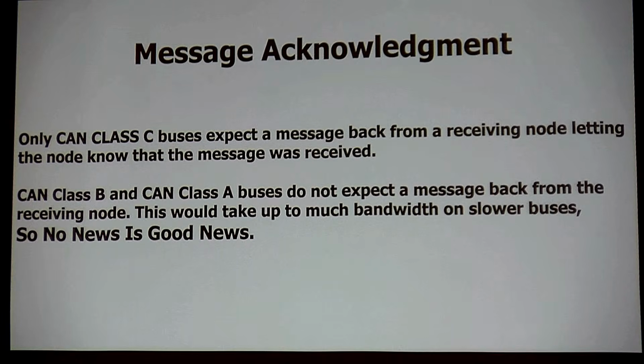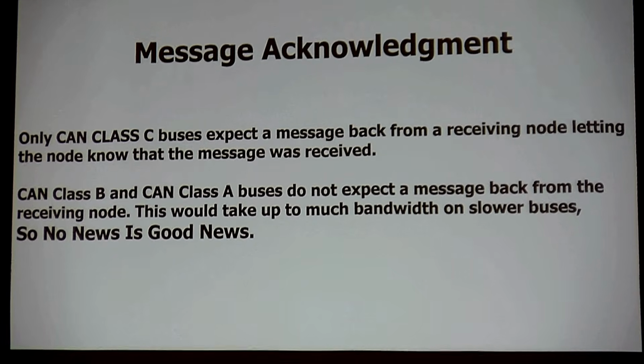So what does that mean? That means if you're on a CAN B bus and you have a module die, you have no code. The guy's dead. He isn't even on the bus, guys. He died, but he died all at once. Does that make sense to everyone? Well, no one expects anything back from him. So you have no codes and the guy's dead.